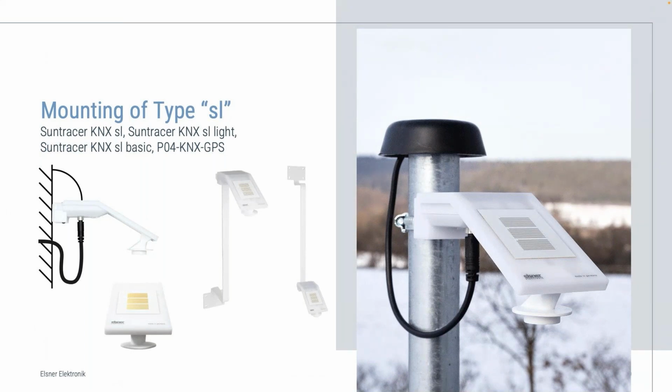So if you have a building that is not too high and you don't need to detect the uprising winds, then mechanical wind measurement is fine. If you have a higher building, then I would always recommend electronic wind measurement. If you have a smaller project, single family home, small villa project, mechanical wind measurement is totally fine. If you need to go higher up on the building, electronic wind measurement is the way to go. I hope I could answer your question there.